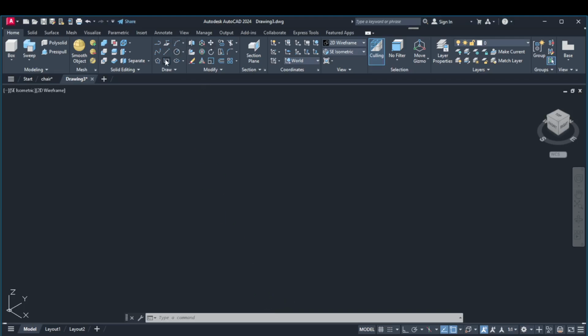Then we pick rectangle, then dimensions, enter. What are our dimensions? Our length is the x-axis, that is 2, enter. Our width is the y-axis, which was 4, enter. So we have this one. We need to click so that it can stick. Then we press pull at a distance of 60. So press pull this at a distance of 60, enter.